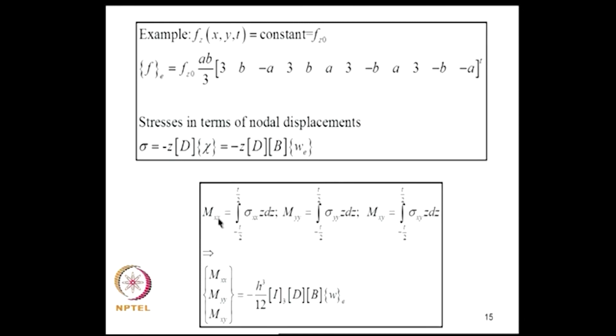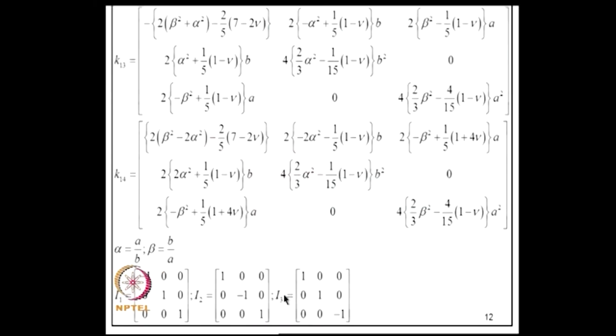Next, if you want to compute bending moments, this is how bending moments are related to the stresses, and we can evaluate this. We have these expressions for sigma xx, sigma yy and sigma xy, and if we carry out this integration, we get these stress resultants that are of interest in terms of nodal coordinates and strain matrix B and constitutive matrix D of the constitutive law. I is a matrix that has been defined here in one of these places.